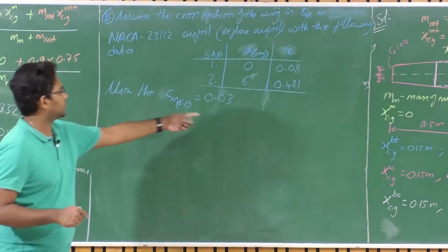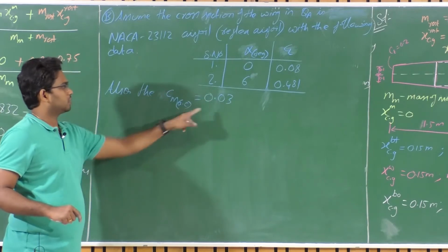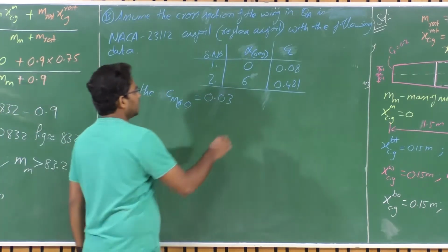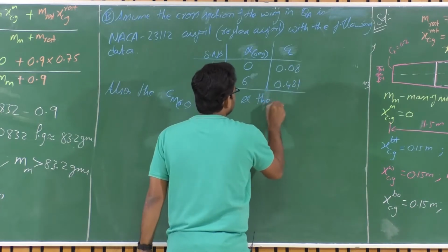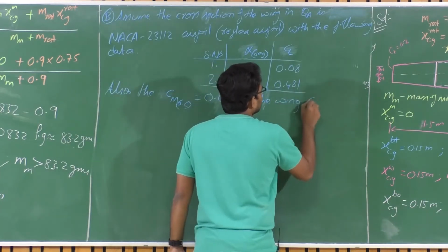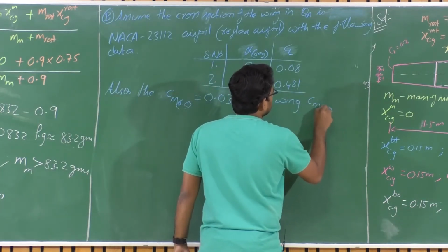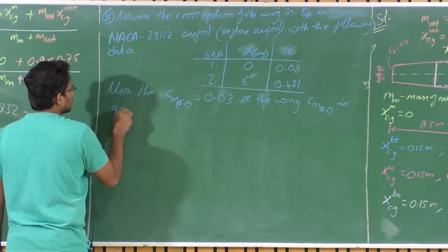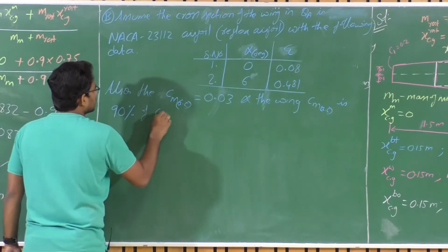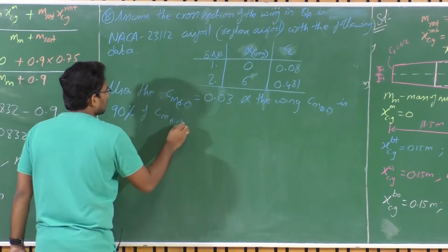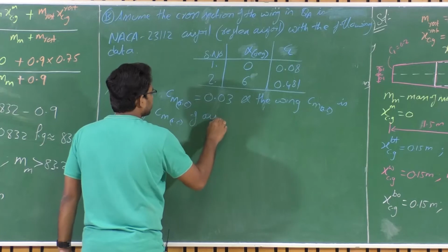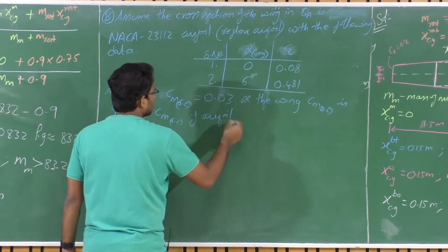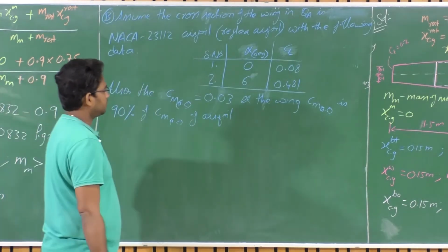We can immediately see that CMAC is positive, it's a reflex airfoil, and consider the wing CMAC is 90% of the airfoil CMAC.